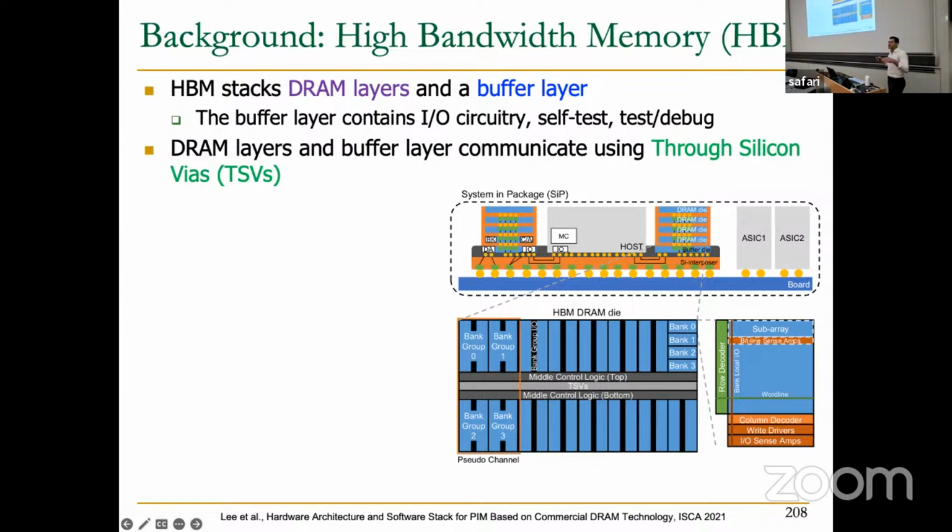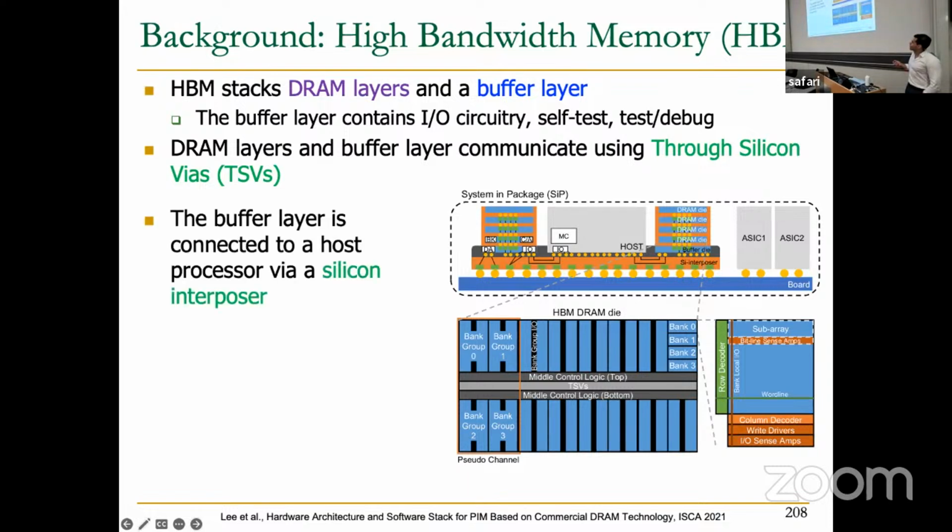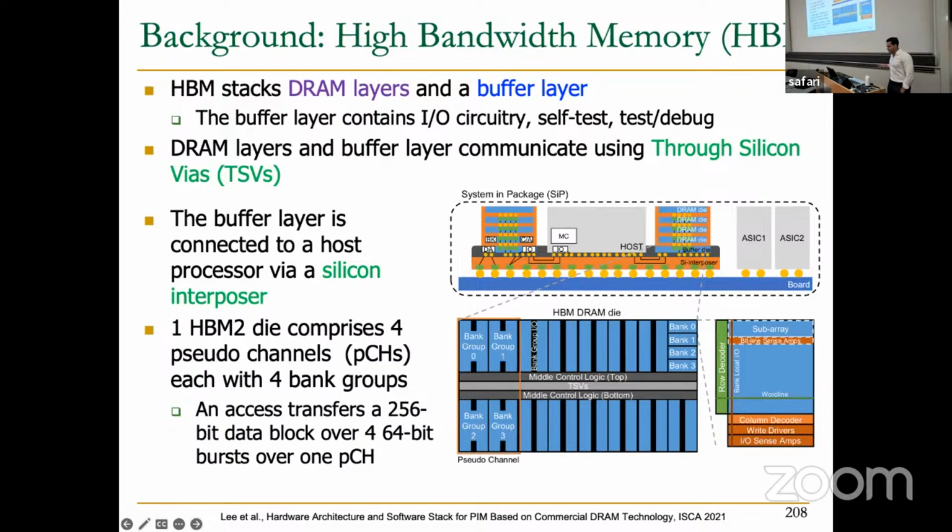That is used, this thing here that connects the host and the die in the silicon interposer. So this is a little bit different from the DIMM form factor, because you cannot plug and unplug. So you put the die, you put the device in the package, and once it's there, you cannot remove it. But this is what we would buy, for example, well, we will not buy because it's nowadays impossible to buy anything from NVIDIA because everyone bought already. But this is what you would get from an A100 NVIDIA GPU chip that uses those HBM chips to provide high bandwidth for their high-end GPUs.